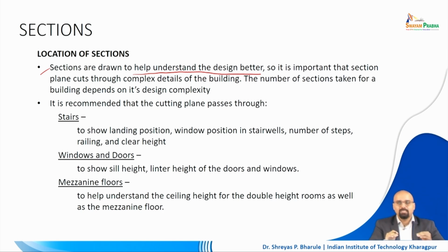So all of these things need to be taken care of in a very critical manner, right? You will have a lot of things to manage with the heights. For example, the height of your basin, the height of your tap, the height of the bulb which will be going on top of the mirror, the height of the mirror with respect to the finished floor level. So all of these are very critical.